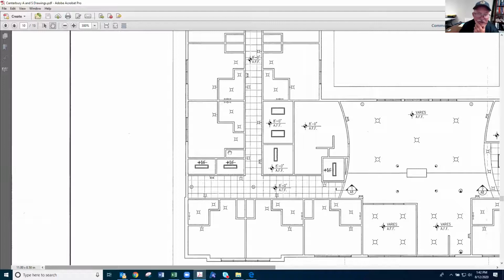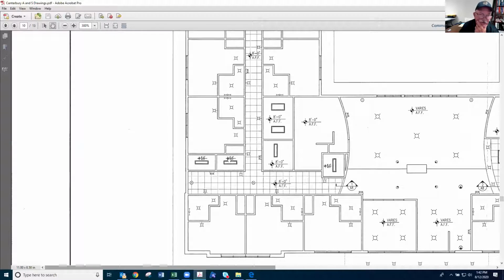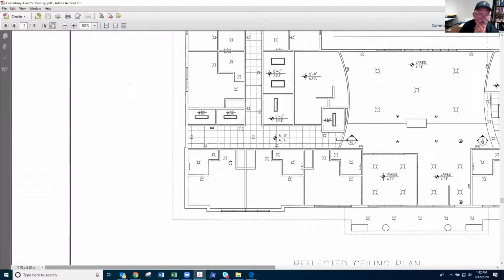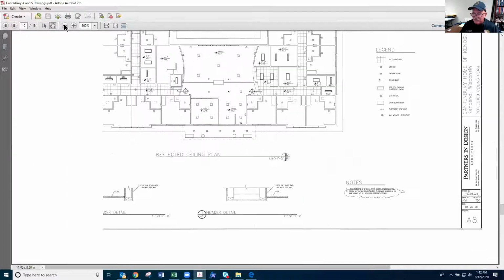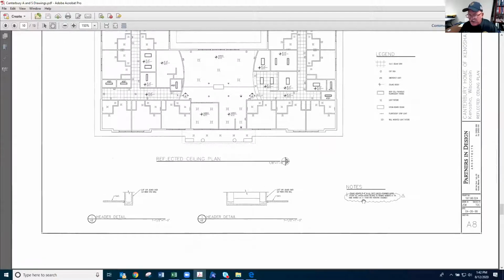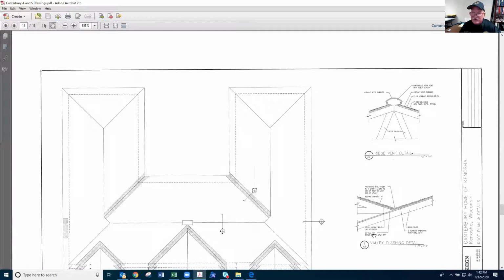So when we look at it, there's a lot of different things that we're looking at in here. Think about the corridors. How long are they? Are they more than 30 feet long? If so, they're going to have to put a hallway somewhere in here to make them shorter. We have to think, even with a sprinklered building, so we'll have to look at our fire protection plans to see that too.